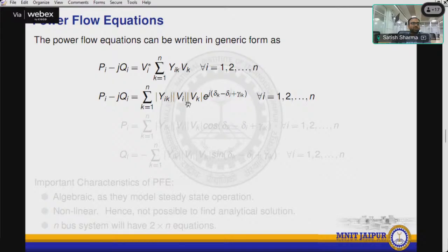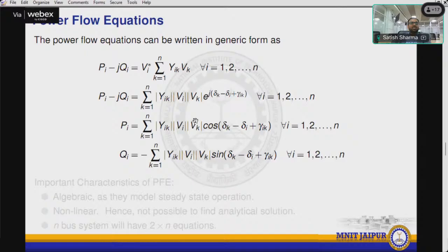So we have taken out all the magnitudes and angles together, and further, if we see, we can convert active power, so active components separate and reactive components separate. So this is Pi and Qi. So this is what I have used, like Vi, Yij and Vj. This is what we have written so far, and then cos of gamma ij, instead of gamma I use theta ij for the angle of Y bus, and then delta i and delta j. So these are basically our voltage bus angles.